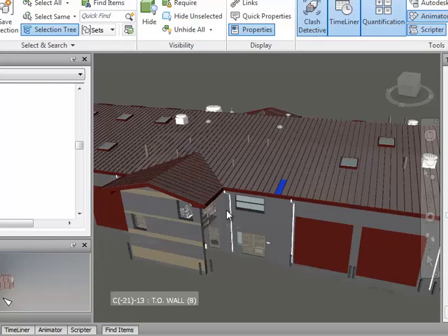Any other questions? So the furniture you buy is in furnishings. If you can pick it up yourself, then it's going to be furnishings. But if you have to nail it to the wall, it's probably going to be casework, which would be Division 6.